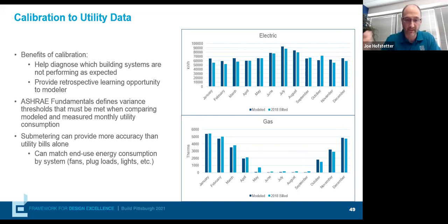And because of that bridging in the insulation, it reduced our wall insulation by about 30 or 35% in its overall performance, and actually had a pretty big impact to the overall energy performance of the building. So that's a perfect example.